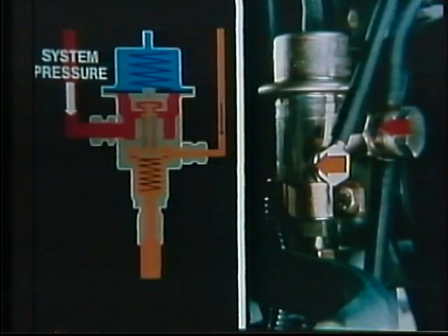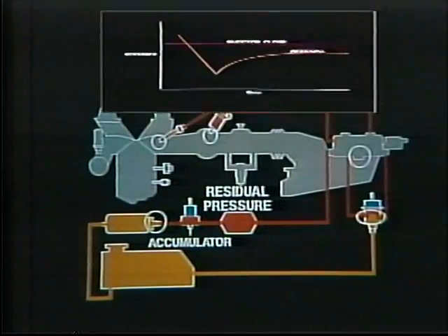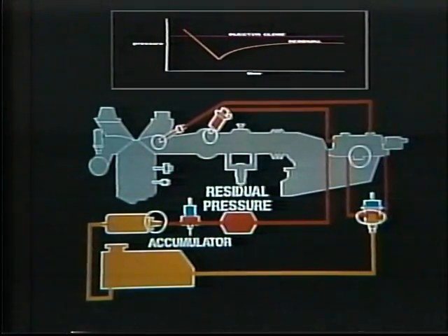the red arrow. When the engine is turned off, the pressure regulator quickly drops pressure, shown by the graph, so the injectors close and seal. Residual pressure is held by the accumulator in all the lines shown in orange. Check the circled points if you have a hot start problem or if the system won't pass the leak test.